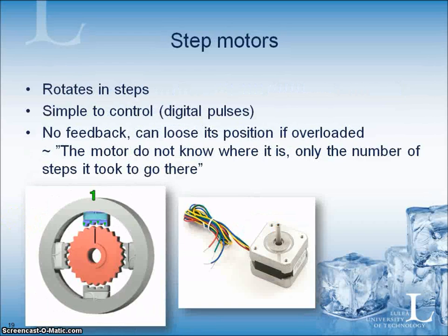In other machines, step motors might be very useful. It's called a step motor because it rotates in steps. It's quite simple to control. You use digital pulses. The problem with the step motor is that it normally has no feedback system, and therefore it can lose its position if it's overloaded.